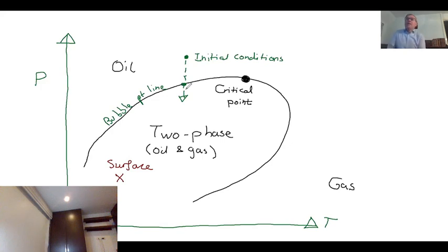But what you notice is if you were to look at this at higher and higher temperatures, the gas that comes out tends to have more and more similar properties to the oil. The composition and the density become more oil-like. The oil, because you're increasing the temperature, is becoming less dense, it's beginning to expand.